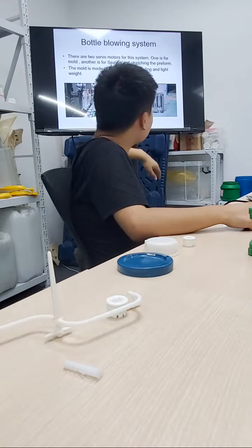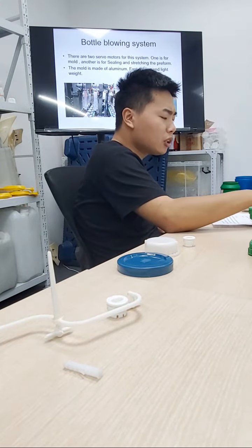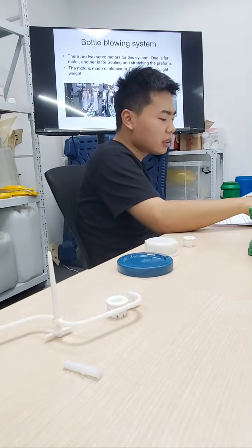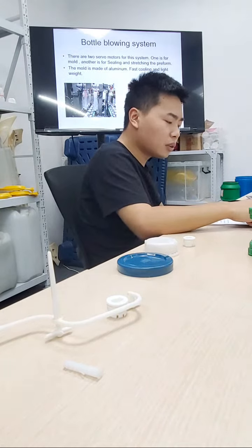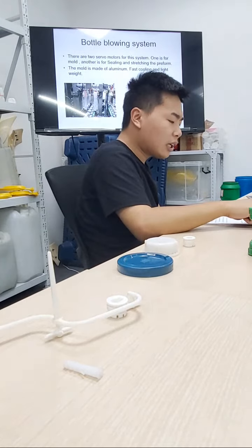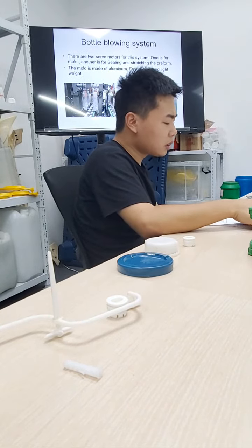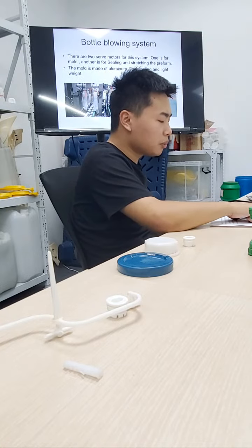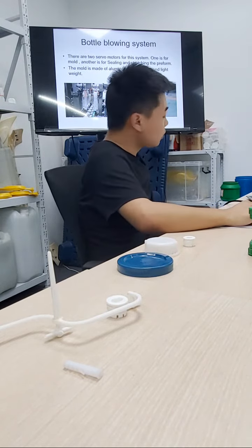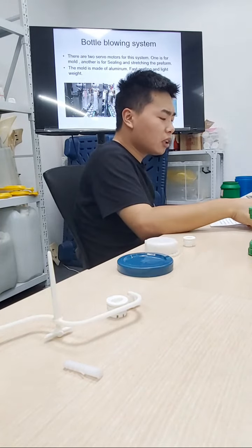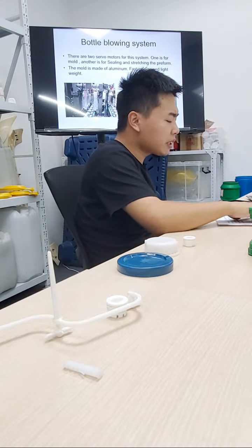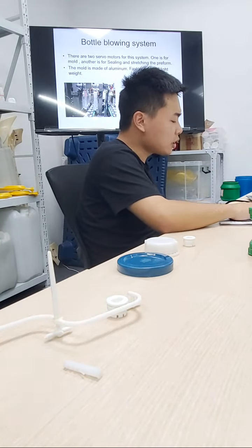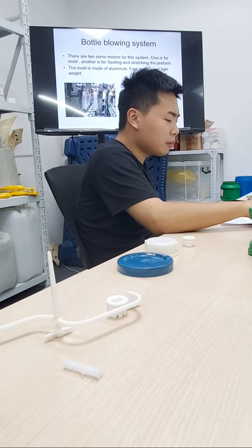This is the blowing system. The blowing system includes the mold, motor, and stretching rod. After the mold is closed, the base underneath will set, and the stretch rod starts to work. It stretches the bottle preform to the mold bottom. At the same time, low pressure gas is blowing in. When the process is finished, the stretch rod goes back. After the low pressure air blows, the preform forms into the bottle shape.